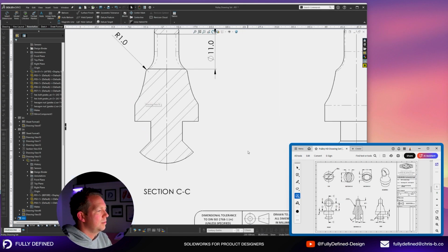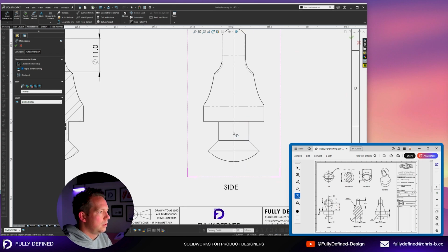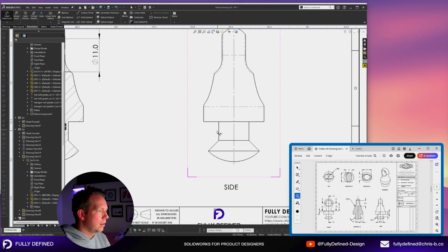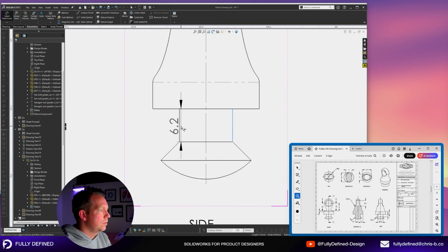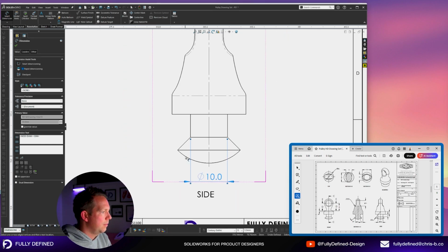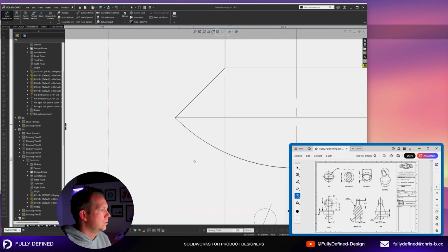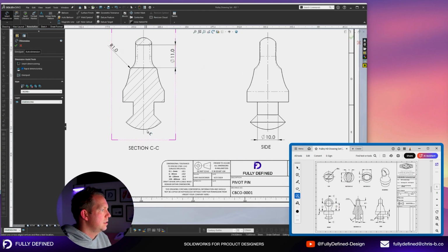But these center lines can be really useful. You can dimension from them. So I can dimension from the center to here, for instance, 5, instead of dimensioning the full width, 10. So it's good practice on this project to add in all the dimensions that you can see on the drawing that I've created. Oof, can't select that edge, that's nasty.